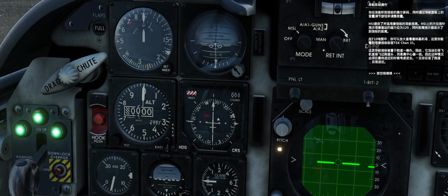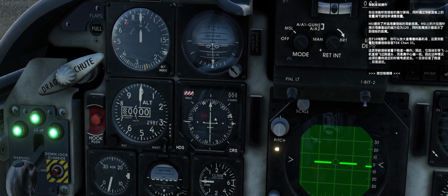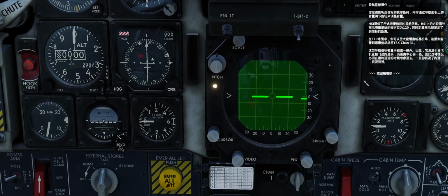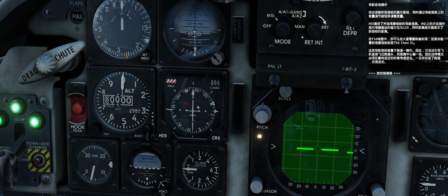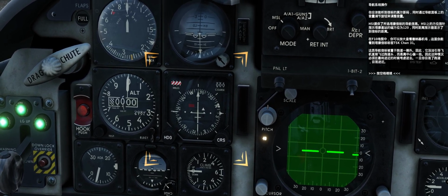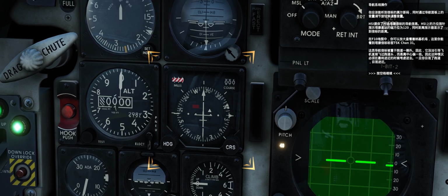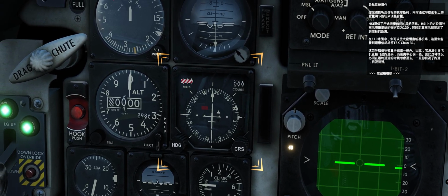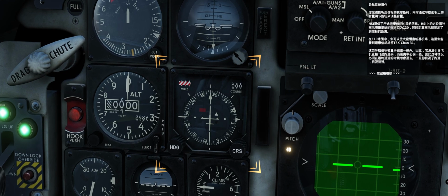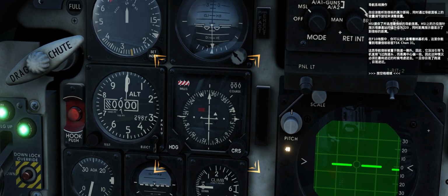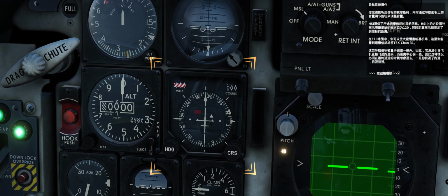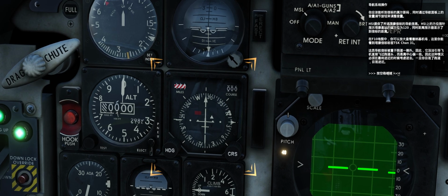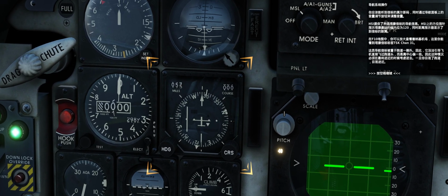Navigation system operation. You should be hearing the beacon call sign, the volume of which can be adjusted using the volume knob located on the navigation panel. The HSI provides navigation information to the selected TACAN beacon. The triangle bearing pointer on the HSI shows a magnetic bearing of 120 degrees to the selected TACAN station, and the miles range indicator shows the distance to it.